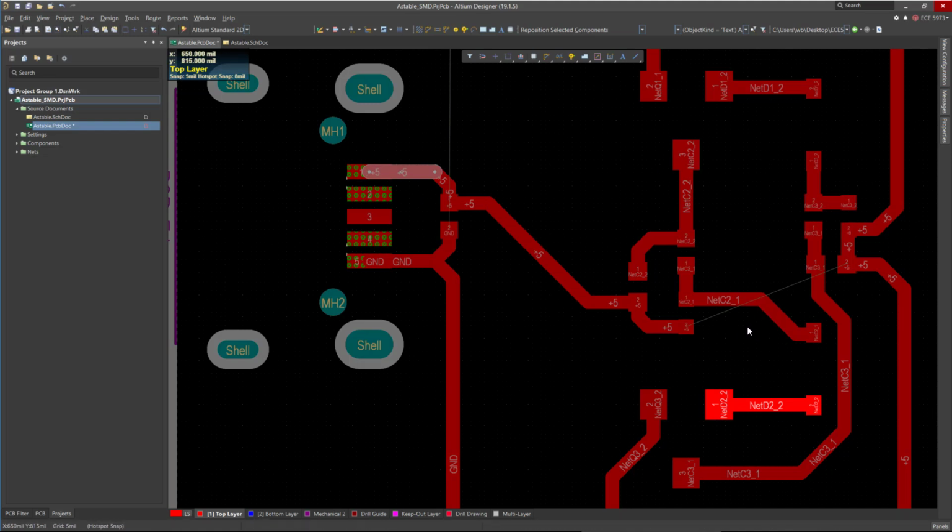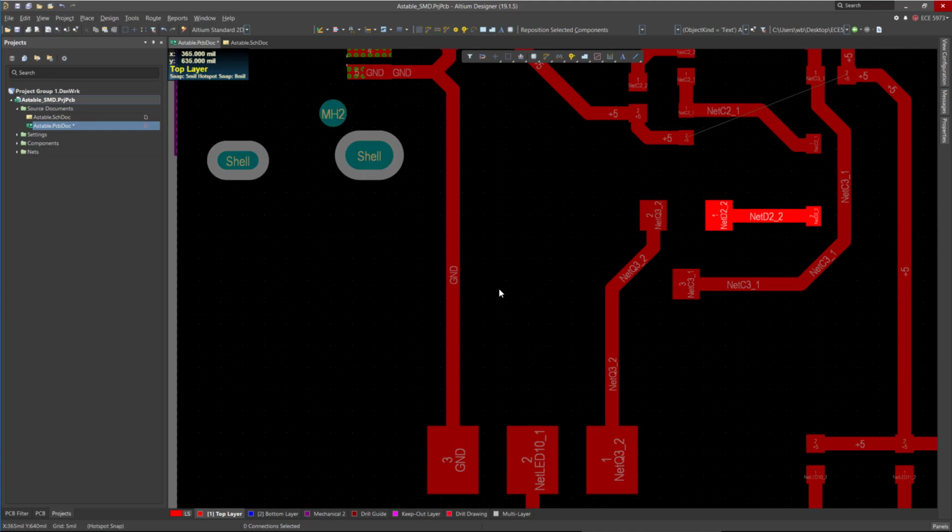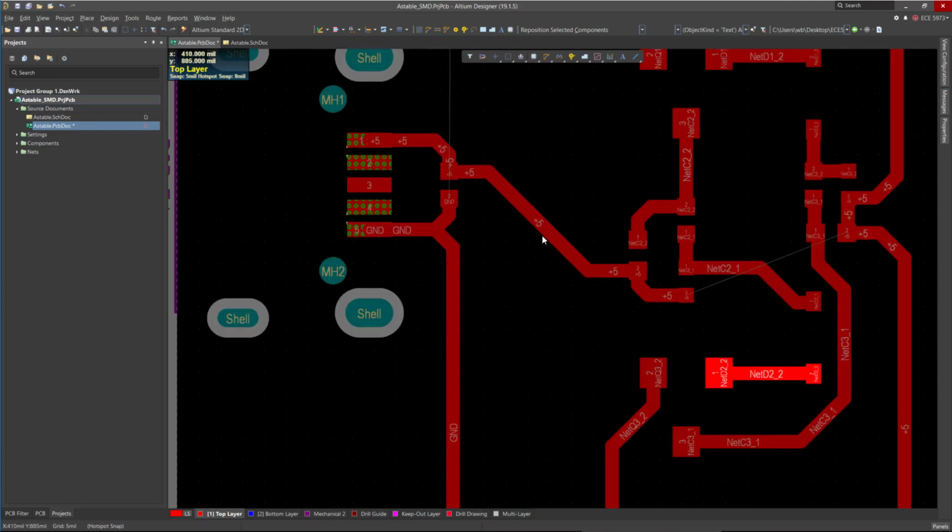And also this is one of the PCB design considerations we will talk about in one of the sessions in the future: how you can calculate the current capacity of the trace. We can use the calculator in the Saturn PCB design toolkit.